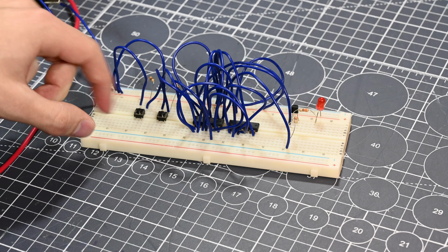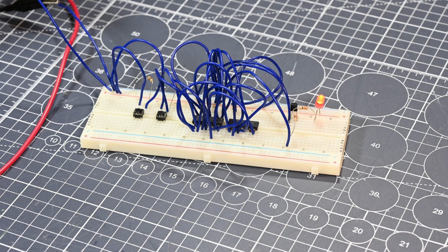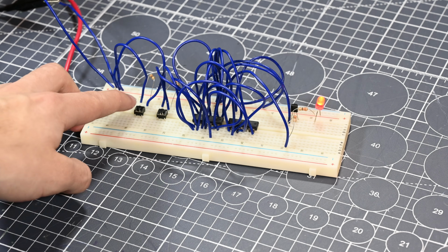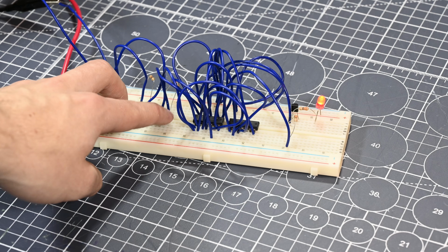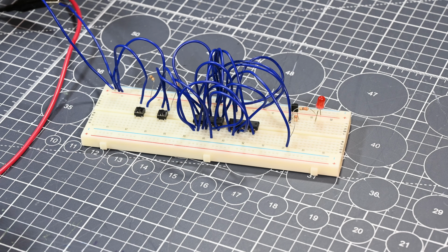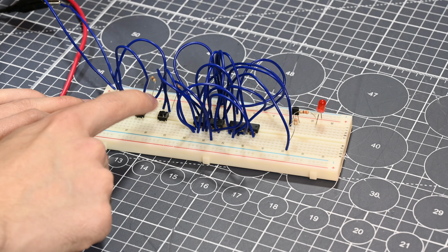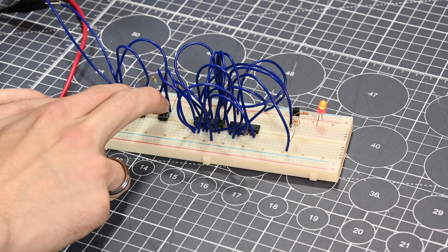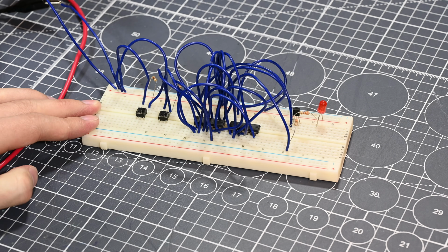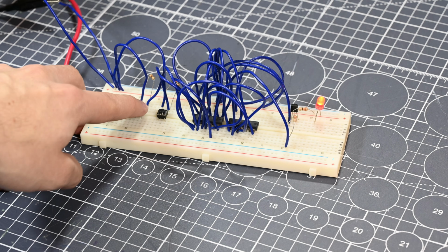When data is put on the data input, which can be either a high or low signal, indicating either a 1 or a 0, the data latch's output will not update until the store signal is pulsed high. Then the data latch will store the value of the current data that it has on its input and won't change the output value until the store signal is pulsed again with different data. As long as the store signal is held low and isn't pulsed, the gate will completely ignore what's happening on the data input and will only output the last data stored.